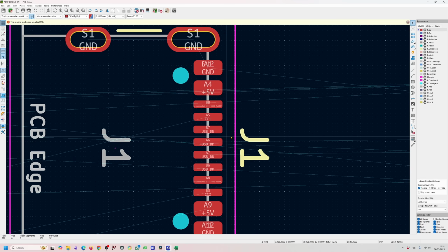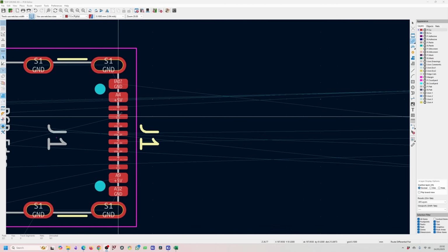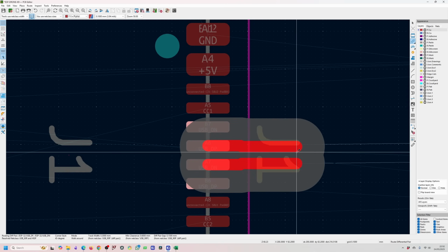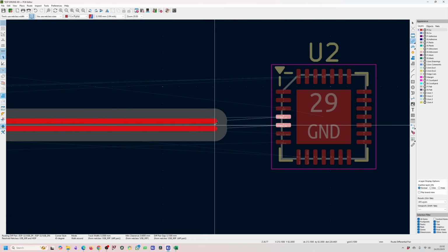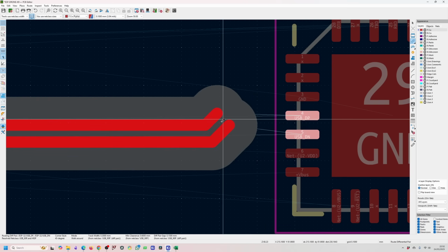And you can see I basically start off with a violation. That's because I don't have enough clearance on this pin to meet this gap over here. But if I start it from here, it will be okay for this case. I'll run into the same problem on this side.